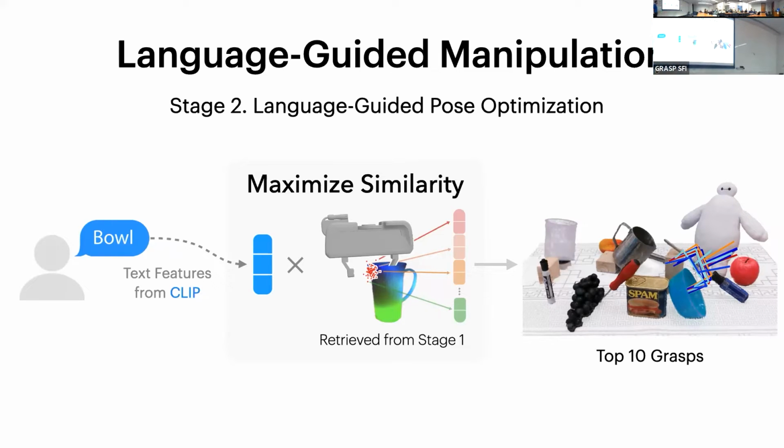What's interesting here are 2 things. The first thing is we're using these human demonstrations as a task-agnostic, or object-agnostic, grasp prior. We're just using the data points to represent the types of grasps we would like the robot to perform, because we don't know exactly what object we want the robot to grasp at test time.